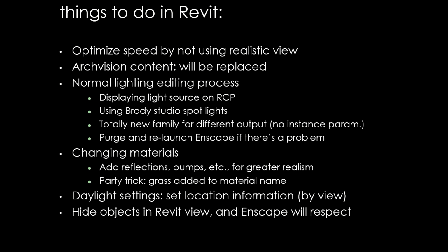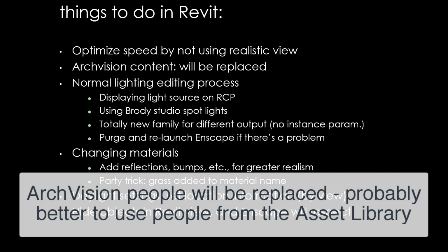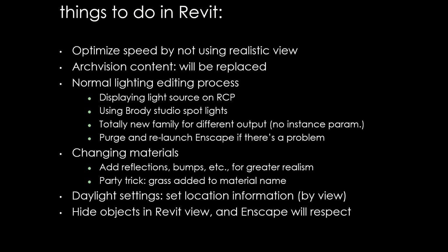Also, if you are on the desktops, not on your laptop, and you're using some of the ArchVision content, it will be replaced with essentially this very similar photorealistic content from the asset library in Enscape. Enscape, I believe, just kind of picks its favorite ones and, of course, use the Enscape asset library directly if you want specific people or specific people at specific angles in your rendering.